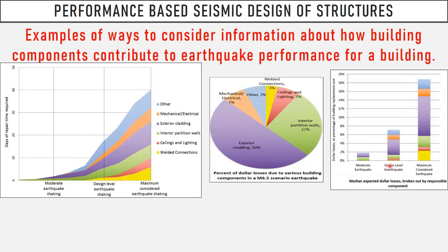This type of approach is more effective to explain to the contractor or the investor or the decision maker whether your design is good or not, or what your design's aim is. Otherwise, they don't understand immediate occupancy. They don't understand life safety. What they understand is something they use in their daily life, which is money, or repair cost, or duration.